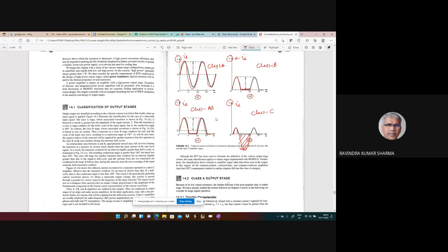अब तीनों एम्पलीफायर में अगर आपको ऐसे मैं बताऊं कि तीनों में जो हार्मोनिक डिस्टॉर्शन है वो किस में जीरो है, यू विल इमीडिएटली से कि क्लास ए एम्पलीफायर में, बिकॉज इनपुट सिग्नल पूरी की पूरी है आउटपुट पर, या IC इज फ्लोइंग फॉर द एंटायर इनपुट सिग्नल, देयरफॉर देयर इज नो पॉसिबिलिटी ऑफ any distortion in the amplitude of the input signal, therefore it has no harm. यहाँ पर obviously साइन वेव डिस्टॉर्ट हो गई, नीचे का पार्ट है ही नहीं, इस डिस्टॉर्शन की वजह से इसमें हार्मोनिक्स जनरेट होंगी, यहाँ पर हार्मोनिक्स होंगी, यहाँ भी हार्मोनिक्स होंगे, बिकॉज साइन वेव इज नॉट कंप्लीट, एंड हियर आल्सो हार्मोनिक्स विल बी देयर. अब इन तीनों केसेस में हार्मोनिक्स को नलिफाई करने का या उनको मिटिगेट करने का कोई मैकेनिज्म यूज करना पड़ेगा, जिससे कि साइन वेव जो ओरिजिनल साइन वेव थी वो हमें मिल सके. करेक्ट.